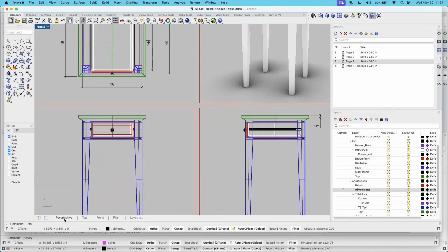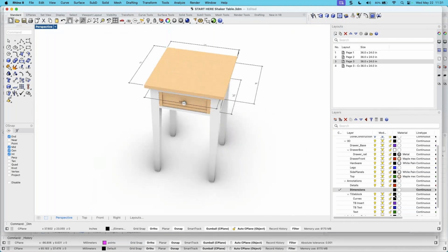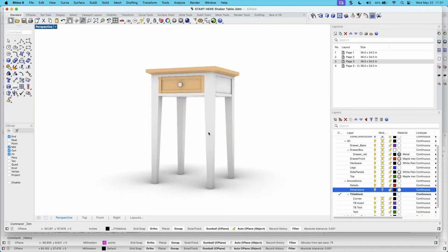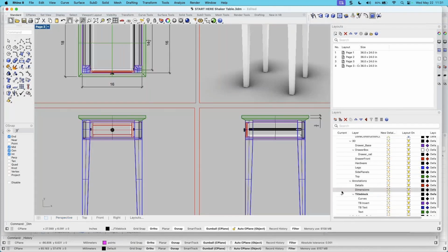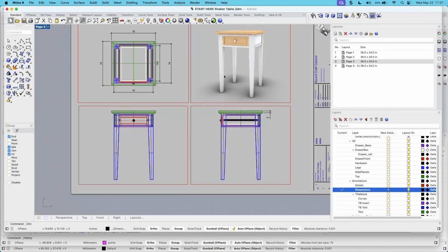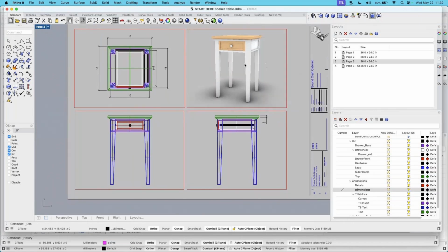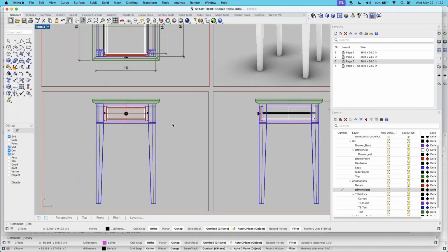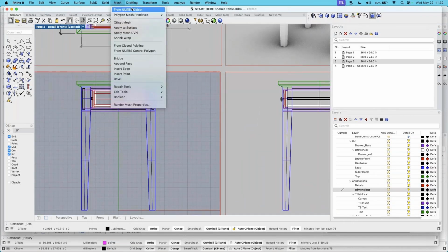Okay, so will this be visible on the model? Let's go find out. I'll go to the perspective view, and if you look in the perspective view, the dimension layer is current, but I can turn it off in the model. So if I pick here, off in the model, then I don't see them in the model. And if I go back to my layout and continue dimensioning, those dimensions won't be visible there. Similar to what we did up here in this viewport where we turned off the dimension layer. Okay, I can double click down here and continue to make dimensions.